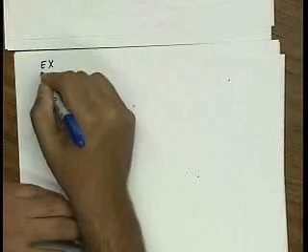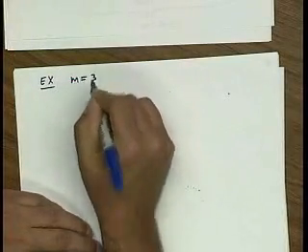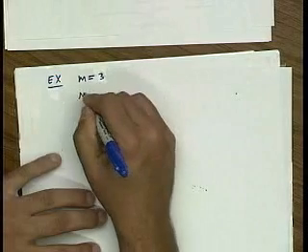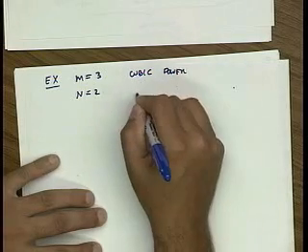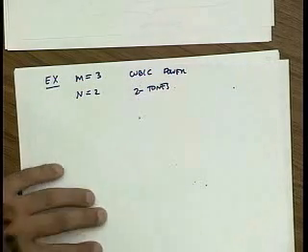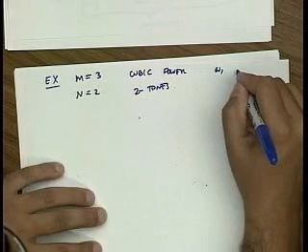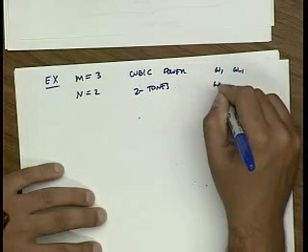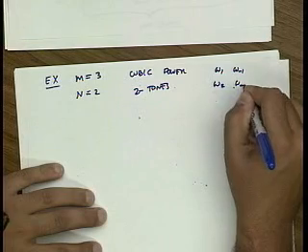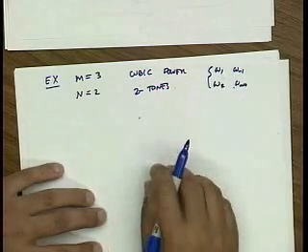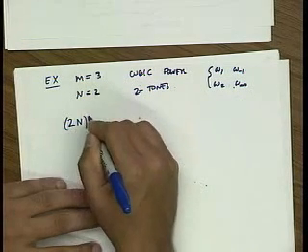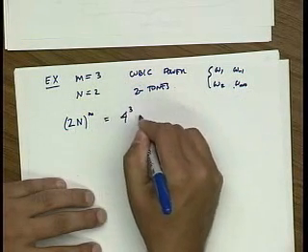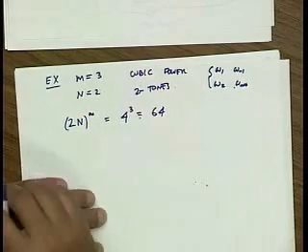Let's take an example to bring this home a little bit. Let me take something simple that we've dealt with. Let me take a cubic nonlinearity and 2 tones. So this is cubic power, 2 tones. And so my frequencies are omega 1, omega minus 1, and omega 2, omega minus 2, which of course is just minus omega 2. So how many terms do I have? I have 2n to the m terms. That's 4 to the 3rd power, or 64 terms.